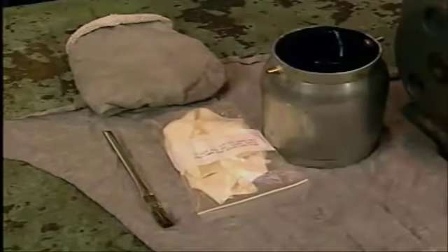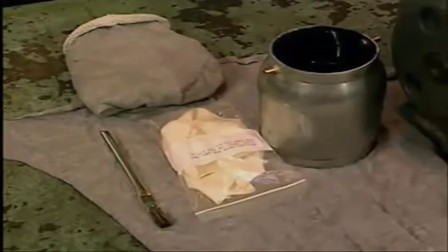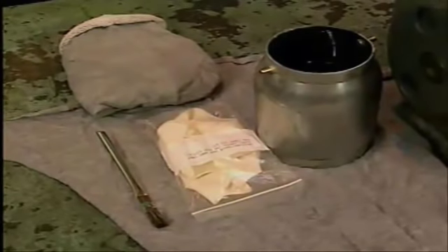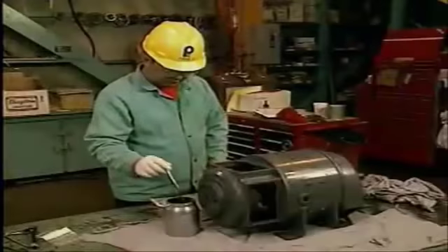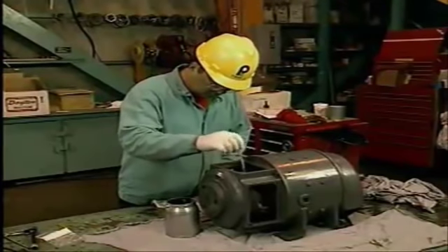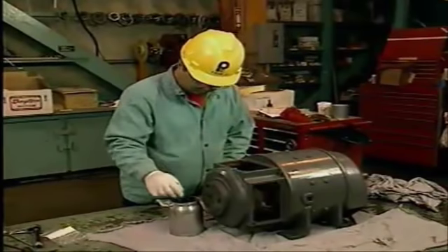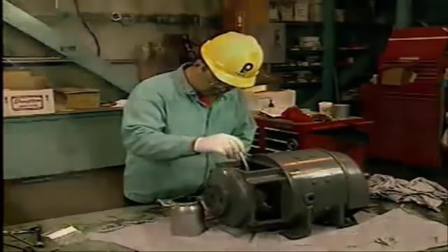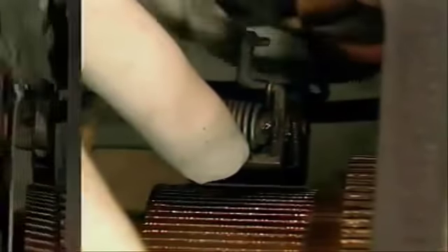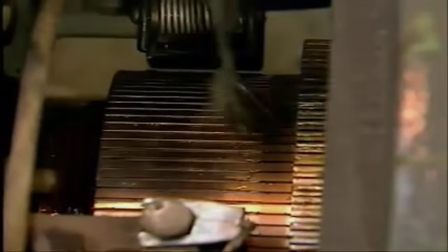Whenever you use cleaning solvents, be sure to follow all applicable safety precautions, such as wearing the proper gloves to protect your hands. During the cleaning step, it's important to pay special attention to the brush holders, the brush tensioning devices, and the commutator. The brushes can be removed from their holders so that the inside of the holders can be cleaned. Cleaning the commutator also involves cleaning the area between the segments. Care must be taken to ensure that the brown coating on the segments is not removed. This coating aids current flow between the brushes and the commutator when the motor is operating.